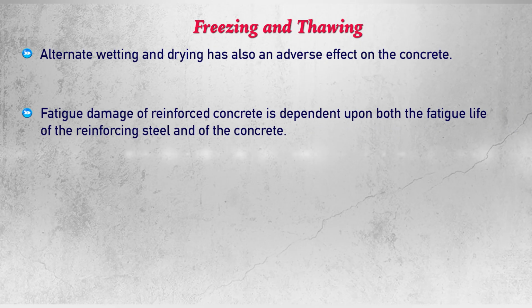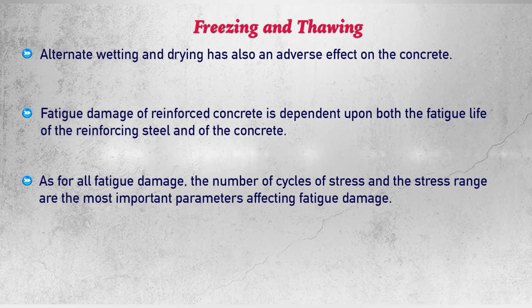Then fatigue damage of reinforced concrete is dependent upon both the fatigue life of the reinforcing steel and of the concrete. As for all fatigue damage, the number of cycles of stress and the stress range are the most important parameters affecting fatigue damage.